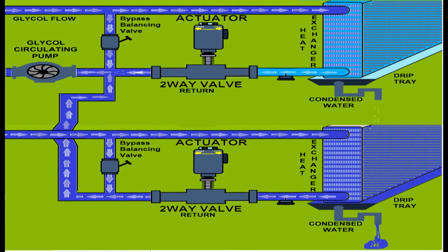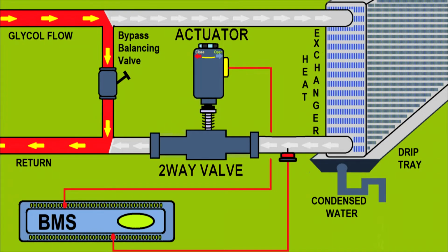So just remember, anytime you want to use an actuator, make sure the use of it is justified. Choose the appropriate system to use actuators. This is a situation in which the actuator and the valve are justified. This is just a branch of a larger system, and I'll give you an example. Let's say you work in a big building with many offices, and this specific branch serves only one office. We will not stop all the boilers because we want to cool down one office. That's why we have this valve. We can restrict the heating agent so it does not pass through the heat exchanger, and then we can ventilate the room through this heat exchanger, and this room will cool down.